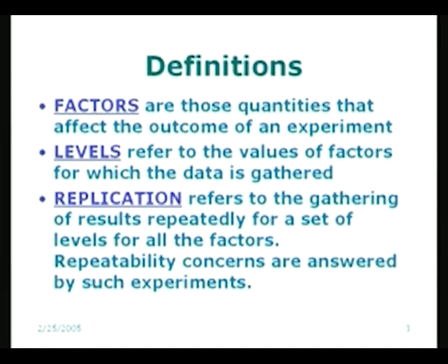I may choose one or two values in between these two limits, and therefore, the number of levels will automatically be equal to the number of values I am going to choose. The lowest, maybe 2 or 3 values in between, and the highest. So, you can have, for example, 5 levels. In another experiment I may have only 2 levels: one is the smallest value, one is the highest value. I just want to see how sensitive the process is to the level of this variable or factor.